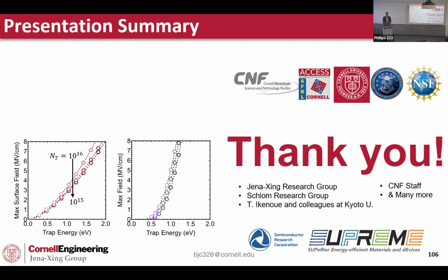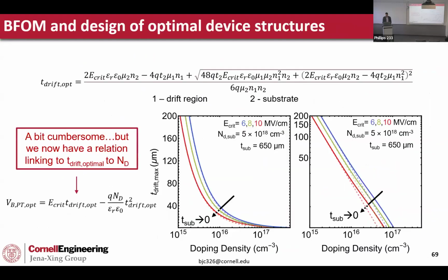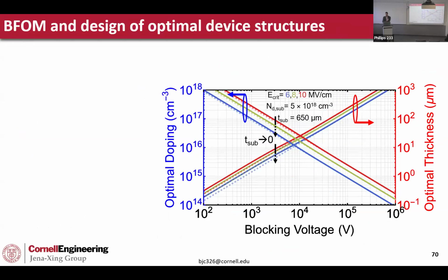John? Yeah, I had a couple questions. In that slide where you showed the optimal doping density and thickness plot, somewhere in the 70s. Yeah. So, the work that's been done in your group and by your predecessors uses doping of say 1E16. And you get, it's 10 microns thick and, say 2000 volts. So are you saying that if you doubled the doping density, you would get an improved breakdown voltage?